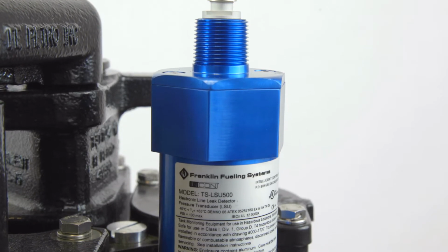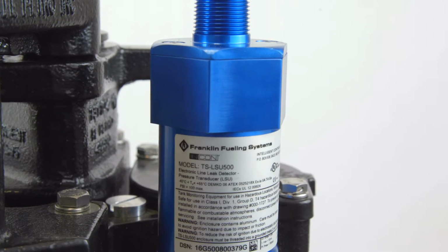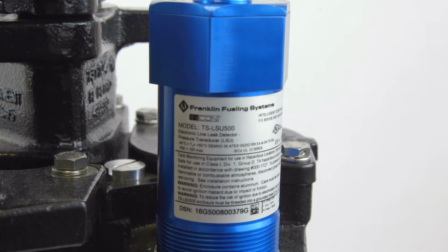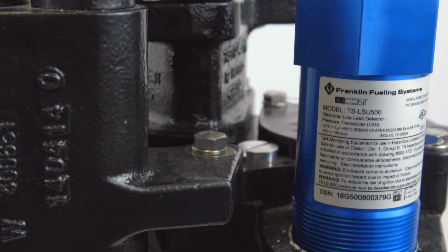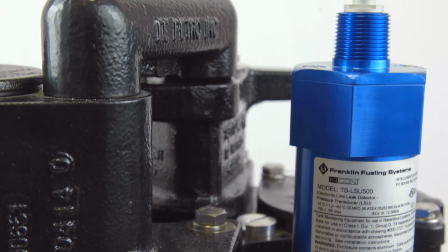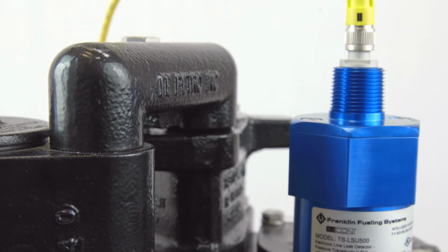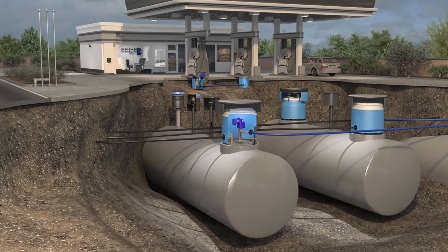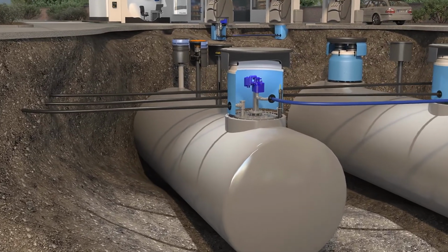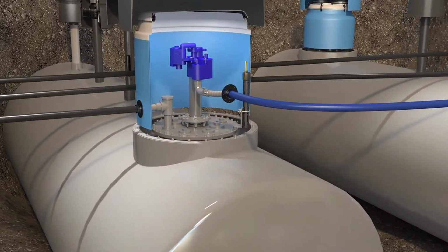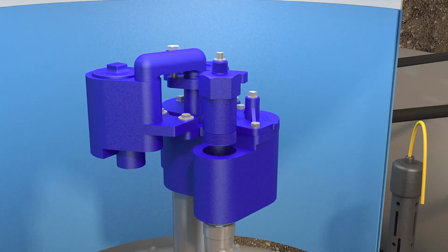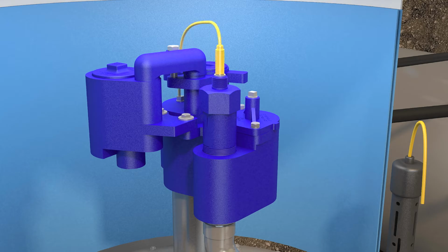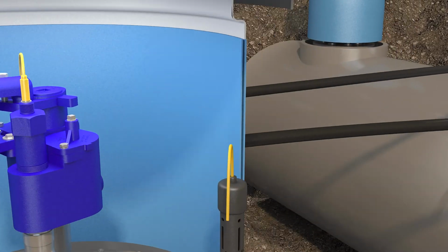We use a leak generator kit which gets installed on the submersible to generate a 3-gallon per hour leak. With that leak generator, we learn the pressure characteristics or decay curve for each individual line. That transducer is installed in the leak test port on the submersible. Fairly quick and easy installation. So once the leak generator is installed, learning the line is very simple.